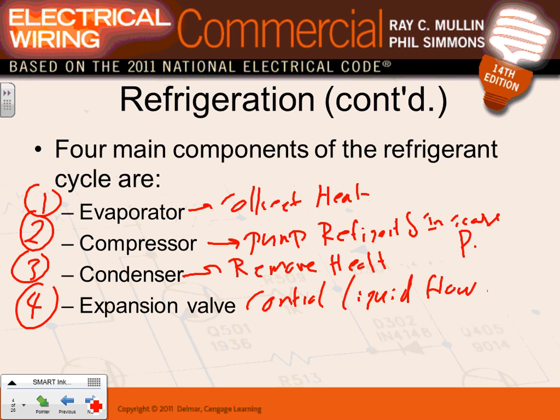Any comments, any questions, guys, about these 4? I guarantee you these will be on the final too. The definitions, just the definitions, what they do for a living. Any comments, any questions about these? How many spelling mistakes did I make? A few? Okay. But these are the most important things, guys. This guy collects the heat. The compressor takes the collected heat and compresses it, increasing the temperature. The condenser removes the heat, and the expansion valve controls the process.